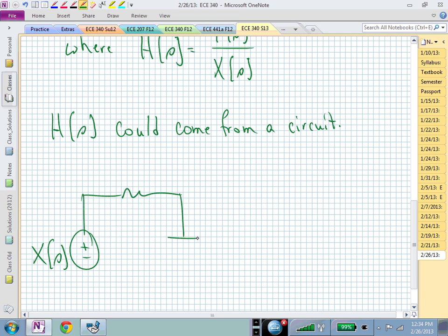We now have, let's say, R sub 1, and now we're doing it in the S-plane. There's 1 over SC sub 1, and what is that right now? If I just worried about what was coming off the voltage across that capacitor, what would you now say you have? You have a low-pass filter.